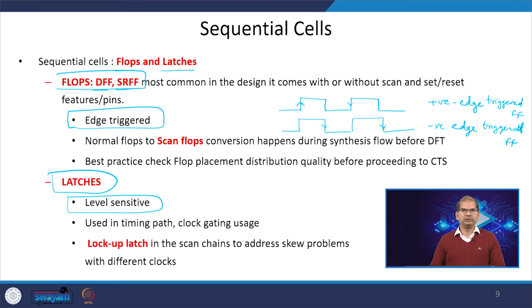In some cases positive edge triggered is required, in some cases negative edge triggered is required, and the synthesis tool will pick based on the requirement. Then we have latches, which are level sensitive. You have positive level sensitive latches and negative level sensitive latches.